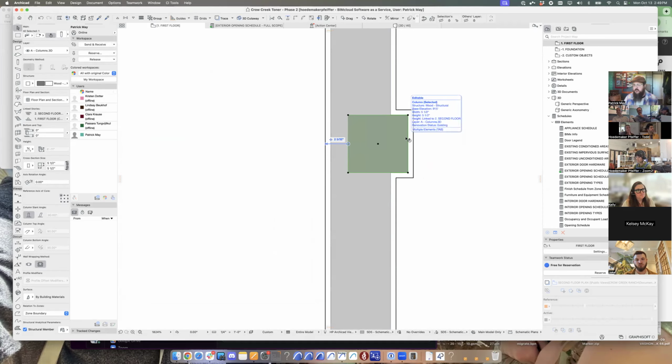I don't know if that's something that you guys run into a lot, but that is a useful tool so that you're not meticulously modeling separate walls or separate columns around those interactions. It's going to automatically identify those two connections. It'll definitely be a thing that we have to address, right? Whenever we're going to clad a column.